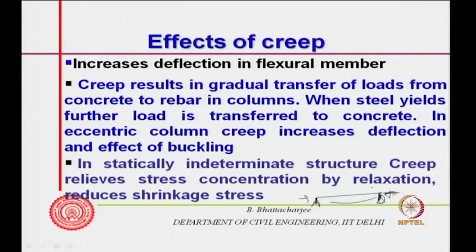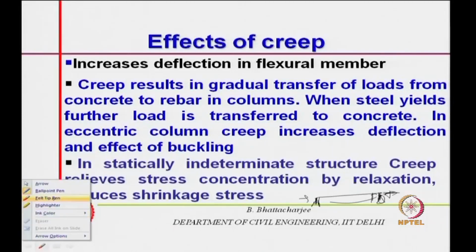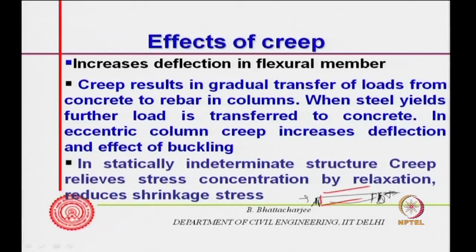Shrinkage stress, for example: if you have shrinkage stress in a restrained element, shrinkage cracks would be tensile, because its natural position is here. After shrinkage it will shorten. We will discuss shrinkage later on, but the shrunk position is somewhere there, but it is restrained. So, there is a tension.